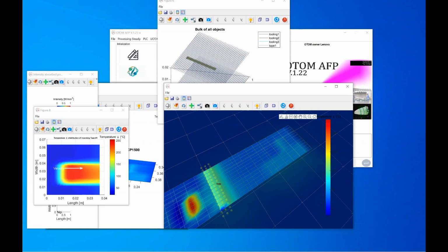These yellow dots indicate that a roller press is happening at these positions. So a roller is actually there in the optical part, but here for the representation we only show the nodes and we consider the boundary conditions of the nodes, which is representative of the roller, with these layers and the tooling below.